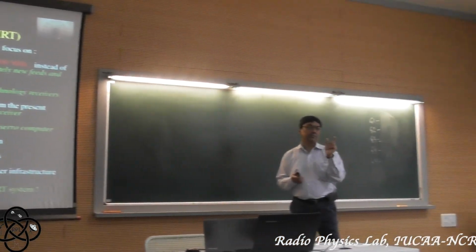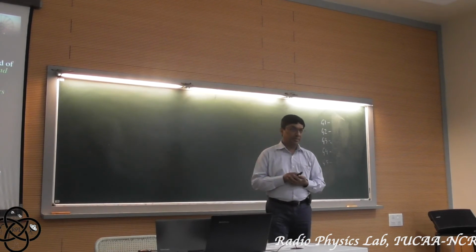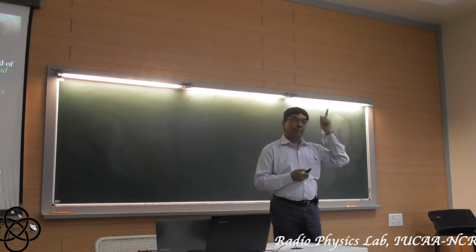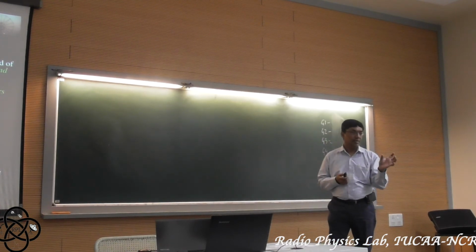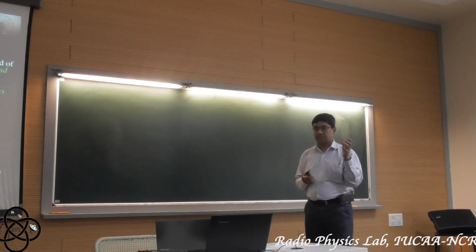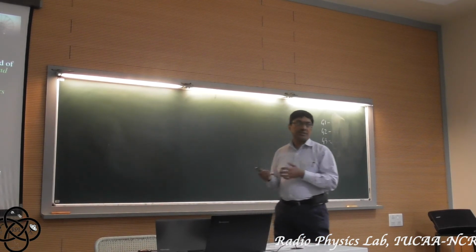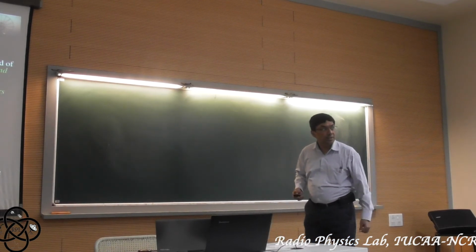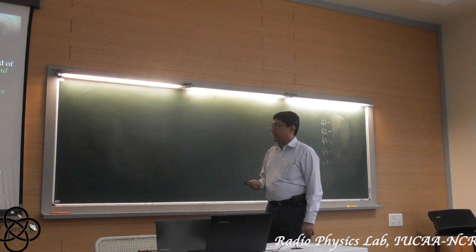So that is that bandwidth, which was 32 megahertz earlier, and the aim has been to increase it to 400 megahertz. You remember again from the very first slide that the larger the bandwidth over which you observe a source at a given time, the more sensitive will be the observations. The whole idea is that you should be able to do much more sensitive observations if you can work over a much larger bandwidth. So these were the main goals driving the upgrade.